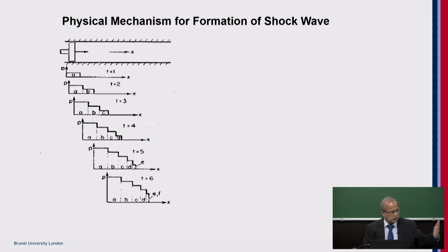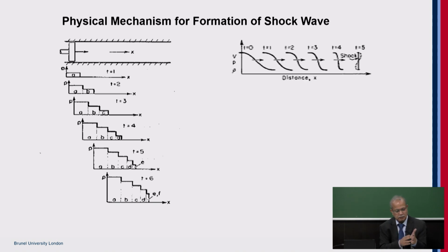Initially at time t equal to 1, the movement of the piston will impart kinetic energy to the fluid particles here. Now that particle energy level will increase, and then the next impact at time t2 will magnify the pressure and temperature of those particles which already had gained some energy. And then in the next impact, you can see that the fluid particles which have already gained impact two times are now being amplified.